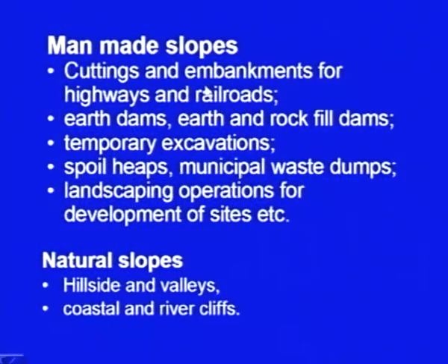In fact, in the case of railway tracks, you have to have a very gentle gradient. You cannot have very steep gradients on railway tracks. So, where the ground is uneven, you have to make the track on a smooth surface. Sometimes you have to cut the slopes, cut the ground, and then keep the railroad at almost the same level. So, cuttings and embankments both come into the picture.